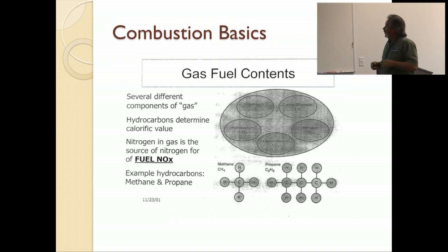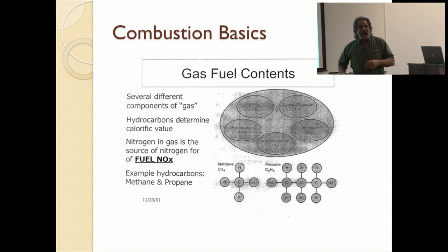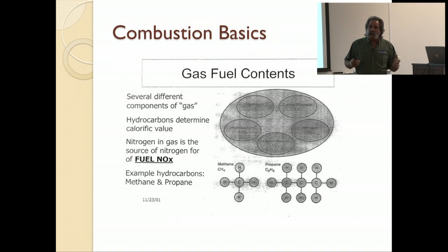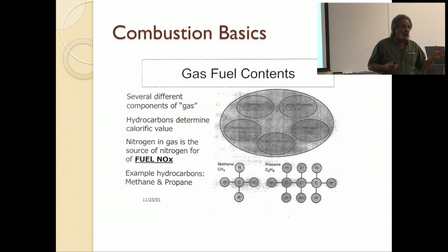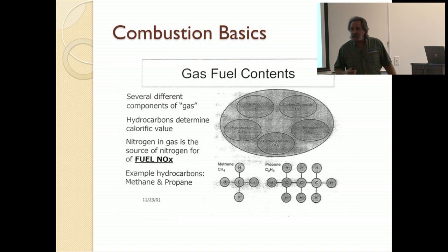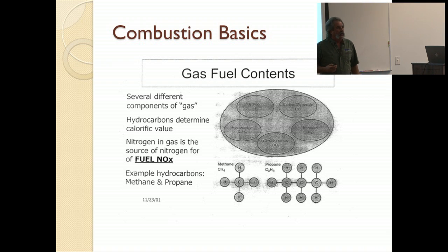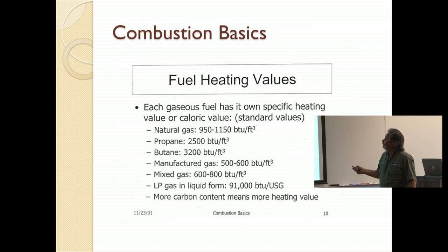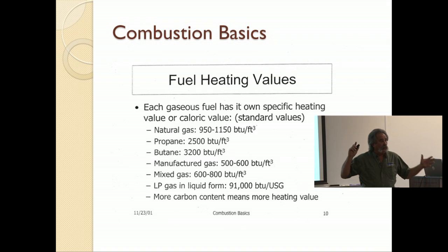The term that's being used, and should be used for all of this, is fuel NOx, N-O-X, and it's nitric oxide. Nitric oxide is also referred to sometimes when it comes down in a precipitative form as acid rain. It was a byproduct in Europe for many years, and that's why they are absolute death on it now. NOx is the single biggest thing that they look at over there. No nitric oxide, period. Whatever it takes, you don't build it. And the way you don't build it is you have a particular style in your boiler of doing this stuff.